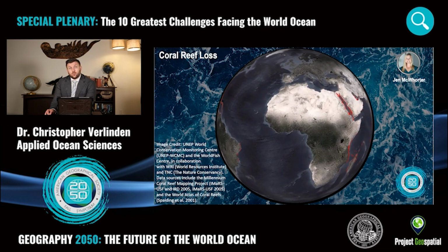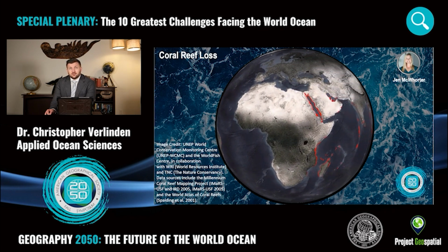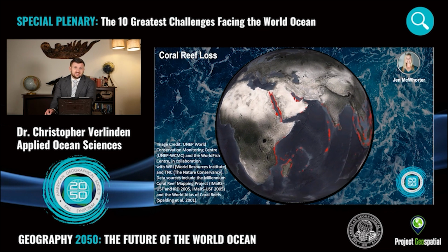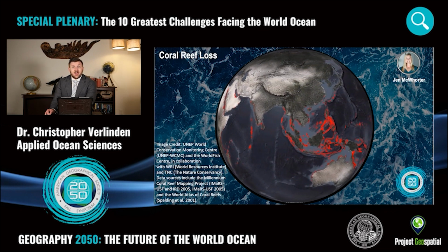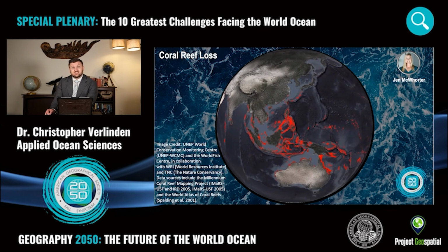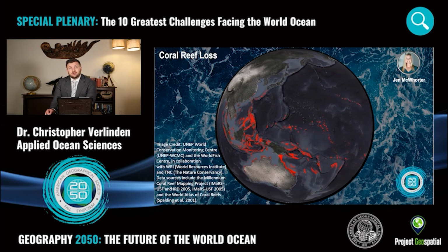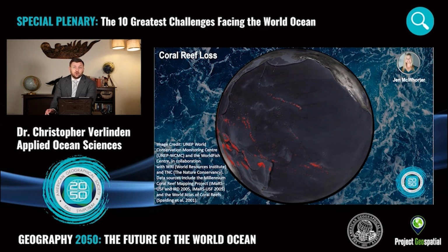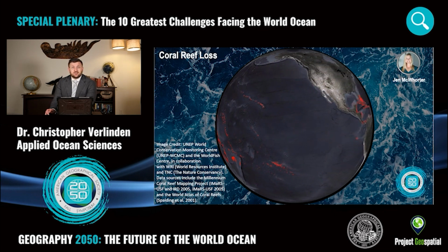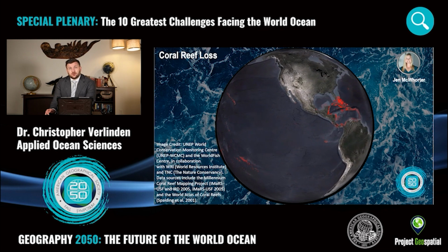By calculating many 1D individual profiles, the model accounts for key drivers of vertical mixing using local bathymetry, tides, and atmospheric inputs, then outputting various column properties such as surface and bottom temperature and photosynthetically active radiation, or PAR. These projections provide a more detailed analysis of frequency and severity of warming events in the future while using relatively simple computing.